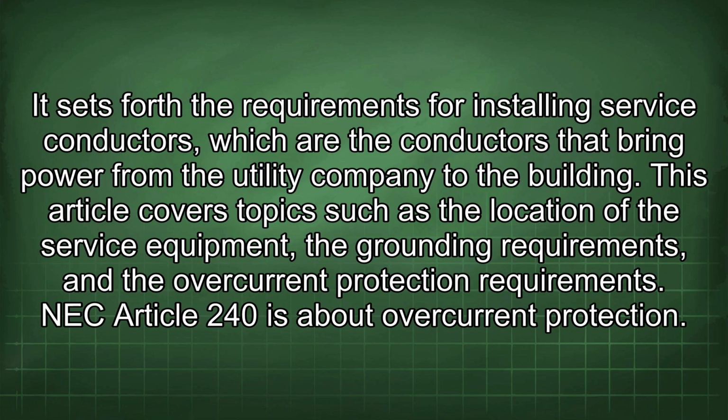NEC Article 230 deals with services. It sets forth the requirements for installing service conductors, which are the conductors that bring power from the utility company to the building. This article covers topics such as the location of the service equipment, the grounding requirements, and the overcurrent protection requirements.